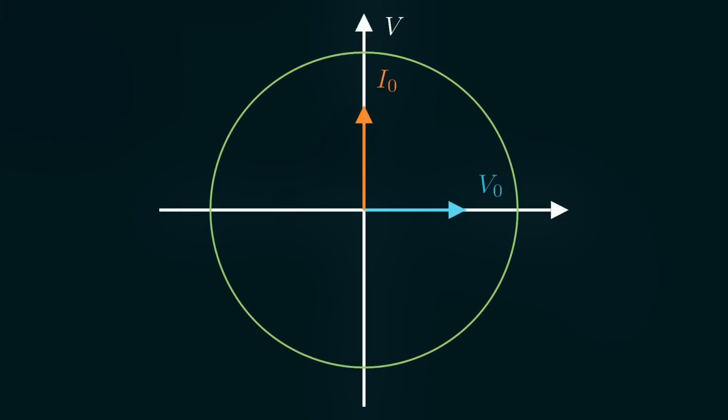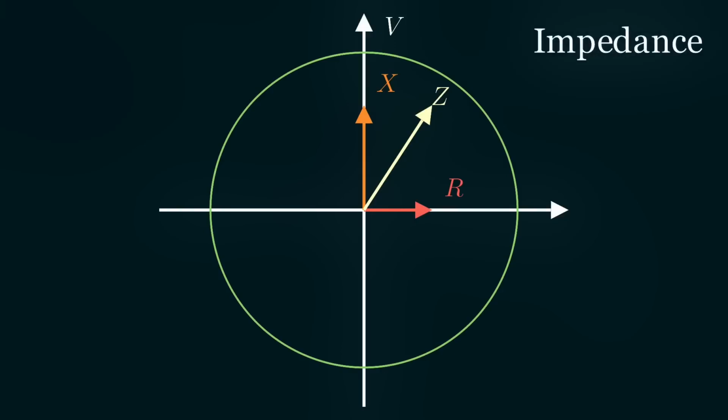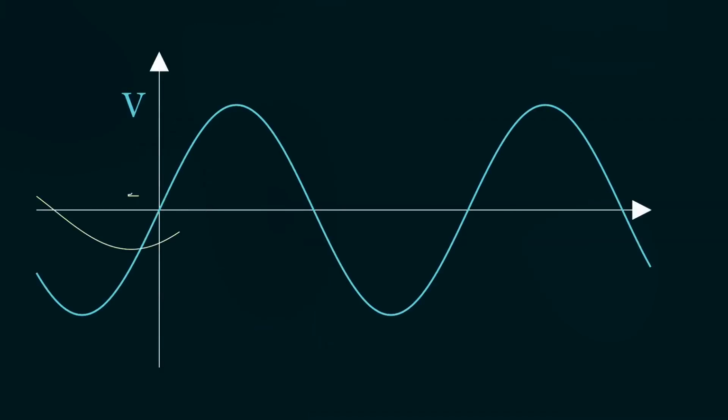Now if you have a capacitor and a resistor in the same circuit, we know that the resistor will follow the voltage, and we also know that resistors in series add. So we can get the total resistance, in this case called the impedance, since it also relies on the frequency, by adding the resistance and the reactance vectors. The magnitude of the impedance is equal to the length of the vectors added together, and since they're always perpendicular, it's the same as the length of the hypotenuse of this right triangle. Z equals square root of X squared plus R squared, where Z is the symbol we use for impedance. So basically impedance measures how much current you get when you apply a certain amount of voltage, but in AC circuits, the frequency also matters, which is why it's a different quantity than resistance.